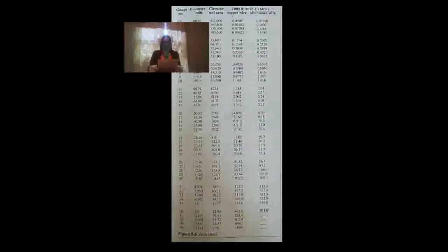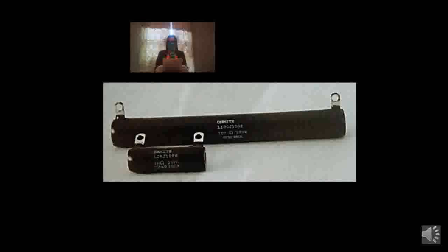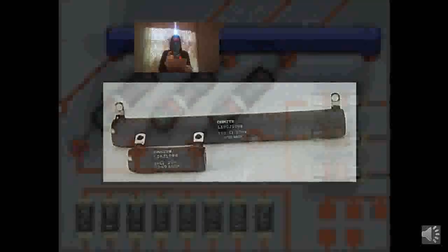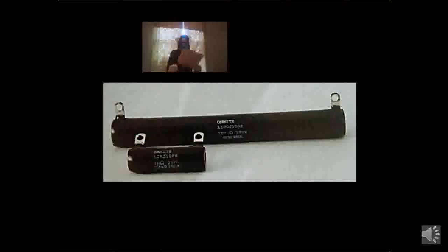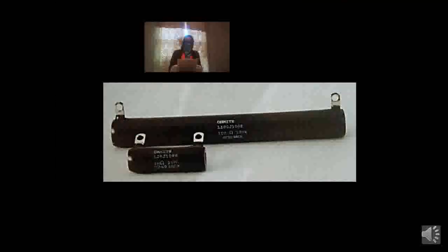For higher current uses, resistors are wire wound. A thin wire is wound on a ceramic core. The wire has a specific fixed value resistance. The entire component is insulated by a coat of vitreous or opaque enamel. These resistors are shown in figure 3-33. The wire-wound resistors are commonly manufactured in sizes from 5 to 200 watts. The wattage chosen depends on the heat dissipation required during operation.